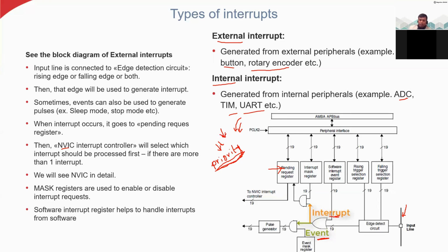But in a microcontroller, we cannot set up the priority on the spot. We need to set up some kind of standard priorities, so we have priority levels. That is what this NVIC is doing. The NVIC sets up the priority for the interrupt signals in this register.